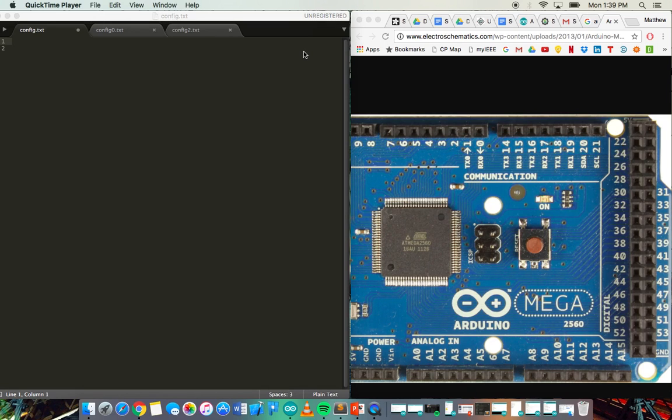Okay, so before we can get the sensor module running, we have to write a series of config files for it. So first we're going to write to config.txt, and this is a file on the SD card in the sensor module that basically contains config information for the whole module. Right now the only keyword in there will be ID, and we'll set that to 1. Basically, the camera module has an ID of 0, and all of its children sensor modules have IDs between 1 and 9, and this is just how we identify which module we want to write to or talk to.